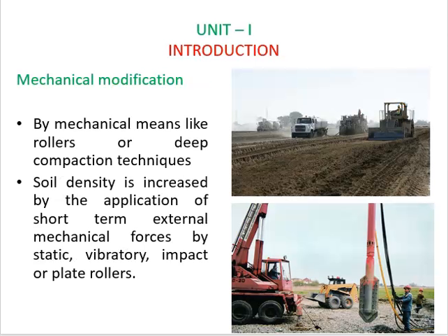So what is mechanical modification? This will be done by mechanical means like rollers or deep compaction techniques. The soil density is increased by the application of dynamic loads using various types of rollers depending on the soil and site conditions.